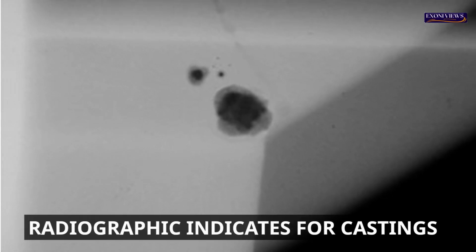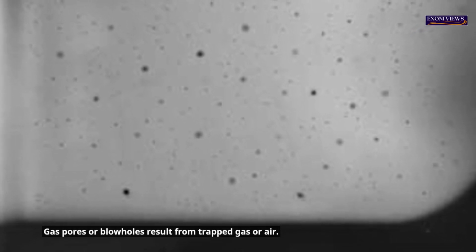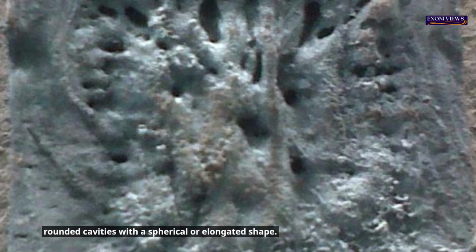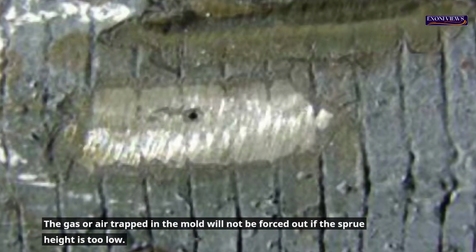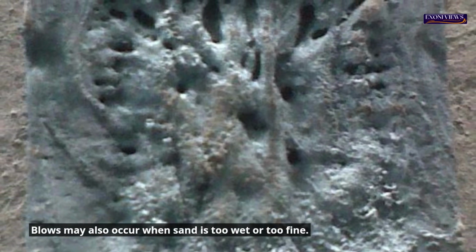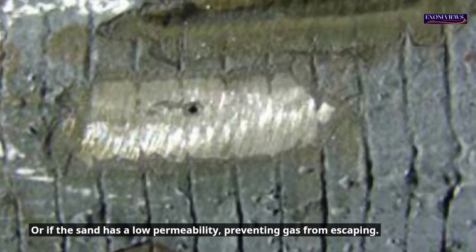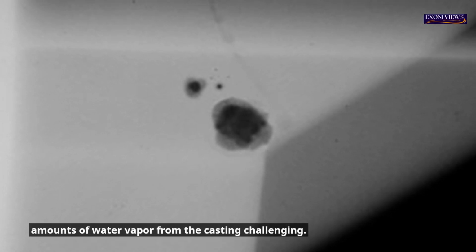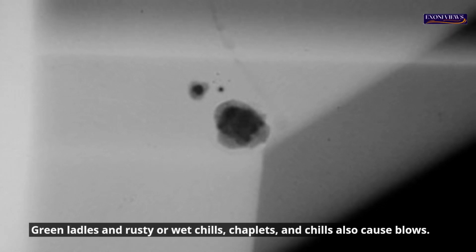Radiographic indications for castings. Gas pores or blowholes result from trapped gas or air. These discontinuities usually appear as smooth-walled, rounded cavities with a spherical or elongated shape. The gas or air trapped in the mold will not be forced out if the sprue height is too low. Blows may also occur when sand is too wet or too fine, or if the sand has low permeability, preventing gas from escaping. High moisture content in the sand can make removing excessive amounts of water vapor from the casting challenging. Green ladles and rusty or wet chills and chaplets also cause blows.